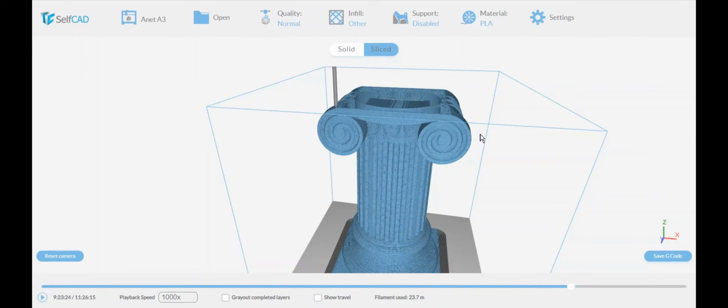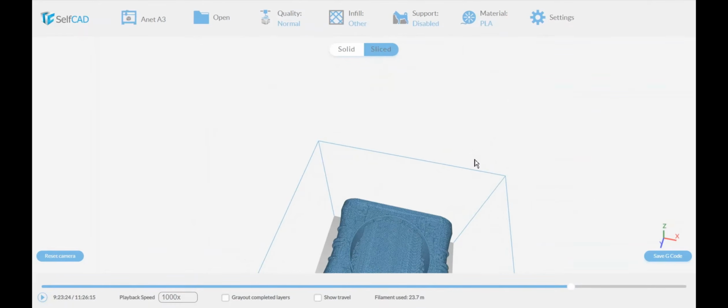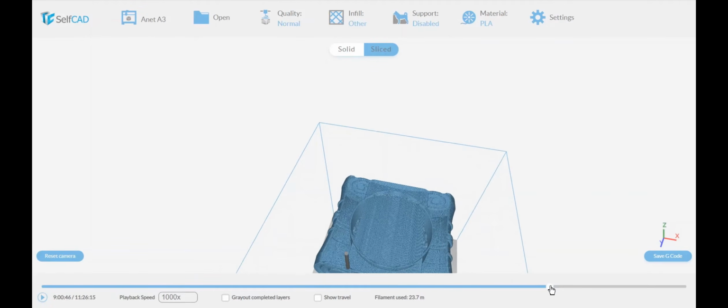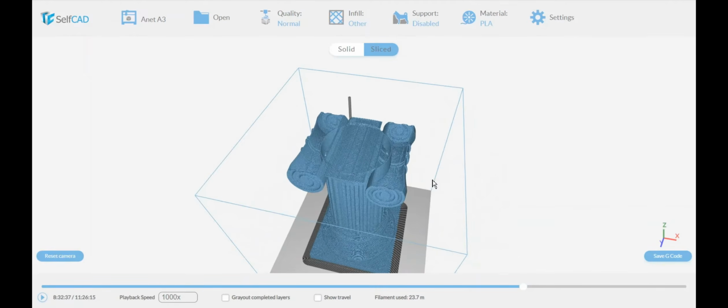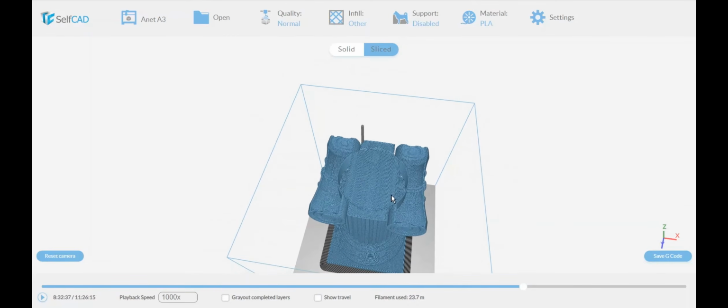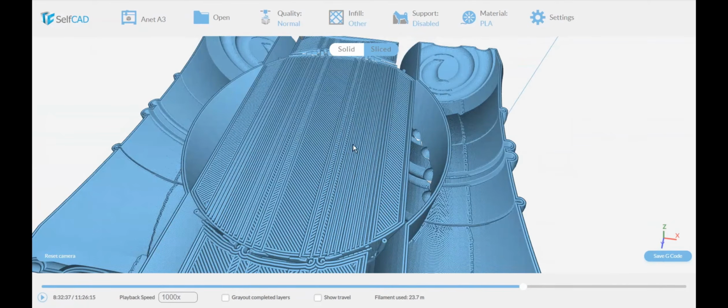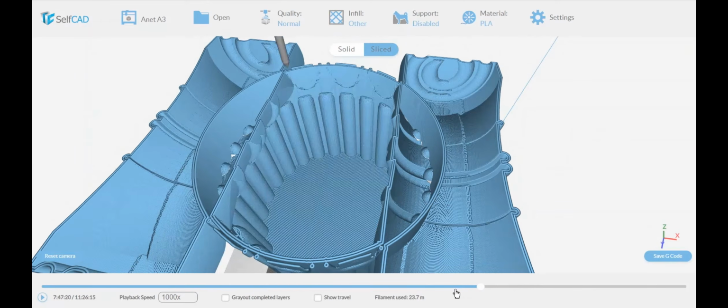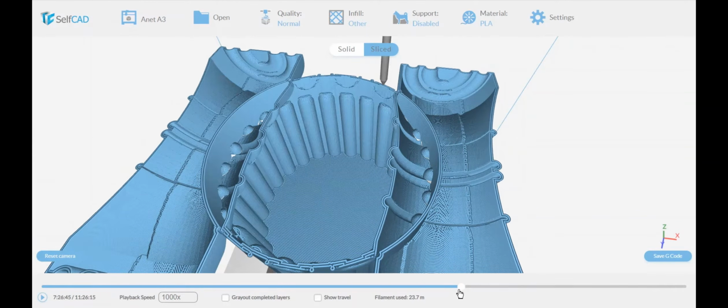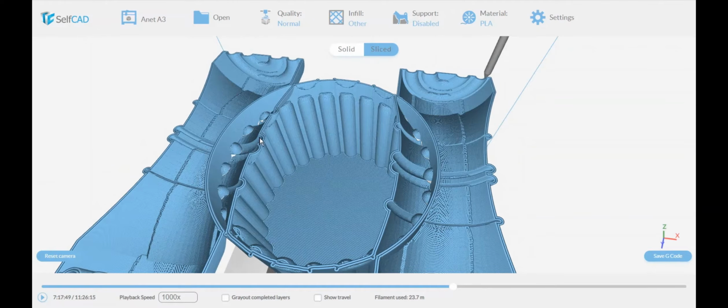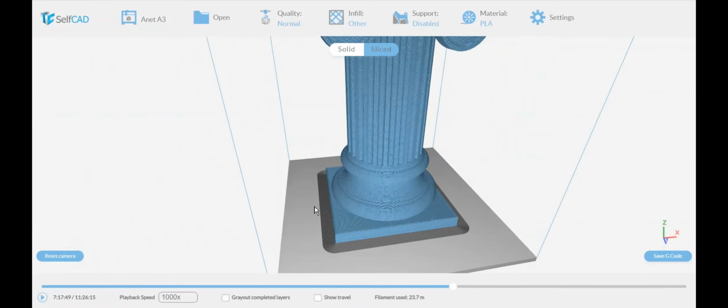Now look at what's happening. Let's go down. You see it creates, and this may create a lot of issues, a section where it prints this entire inside, which is not an infill because we have no infill. And you can also see from the color, it's a different color. This entire section comes inside here, and it's showing everything. So it's very important to note that a lot of times you need to have these types of fixes.